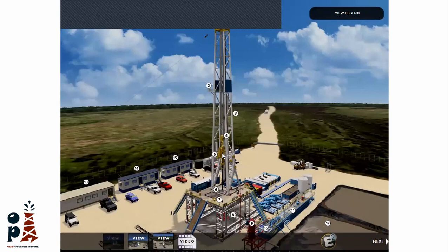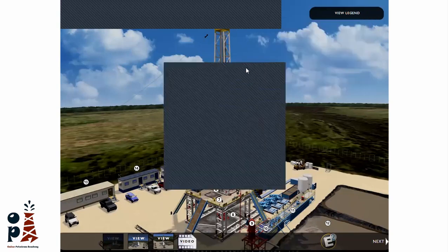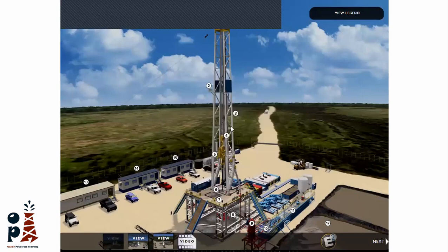The top drive is very important. Maybe 15 or 20 years ago we were not using the top drive, but we were using the Kelly, and it is still used today, but very rarely now, because the top drive is a very powerful tool. We can use it to make a connection of 3 joints, not only 1 joint. In Kelly operation, we were using only 1 joint, so it would take time to make a connection. With the top drive, we can make a connection of 3 joints, which is around 30 meters or 90 feet, and the drilling is faster than in Kelly operation.